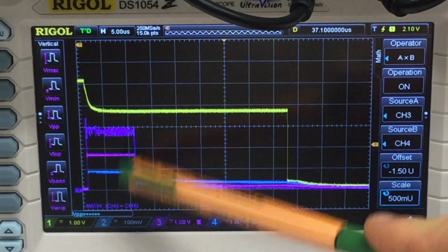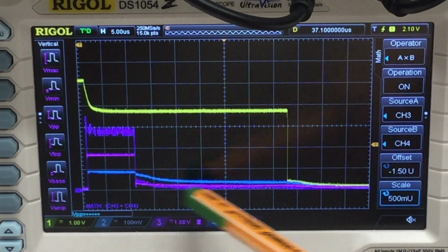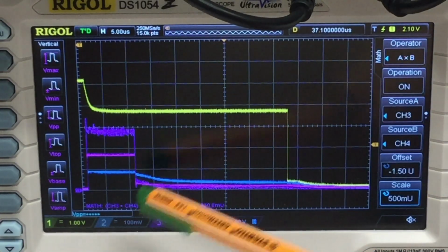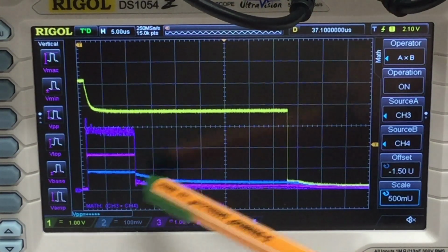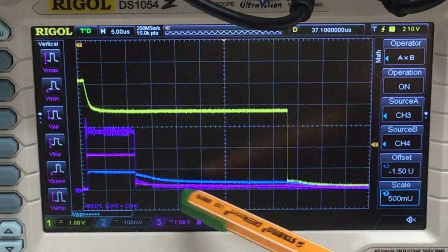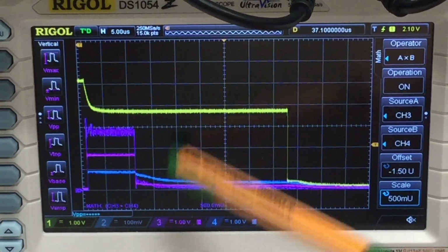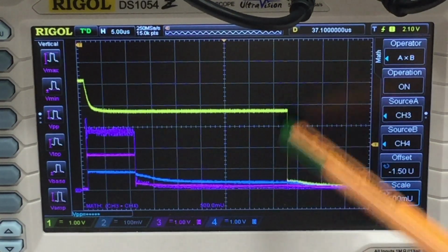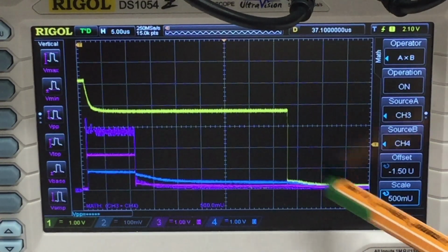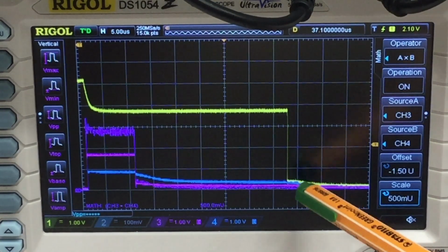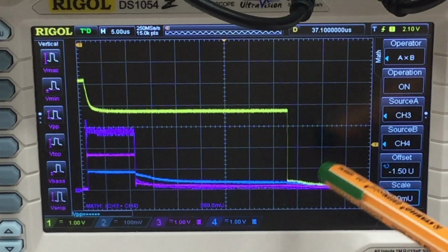So you have actually a voltage coming out of the gate when the TRIAC is in its on state. And here it gradually decreases with some time constant. At that scale, 5 to 10 microseconds. Let's say here while it's on, 10 microseconds. And then when it's finally going back into its off state, it also takes a while to go down. So there's actually current coming out of your gate.